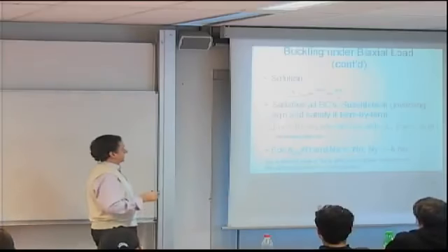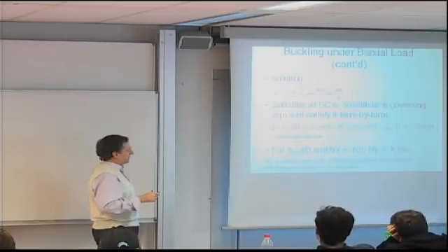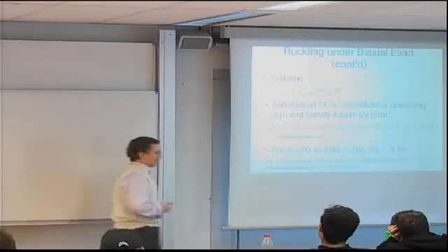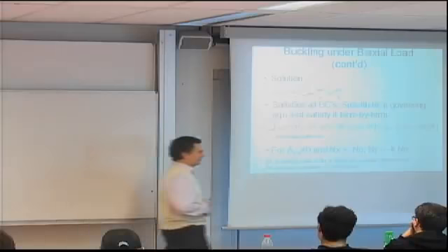So it turns out this is ideal in this case, because by just substituting the boundaries at x and y, 0 and a, or 0 and b, you will find that not only W is 0, but also the bending moments are 0.